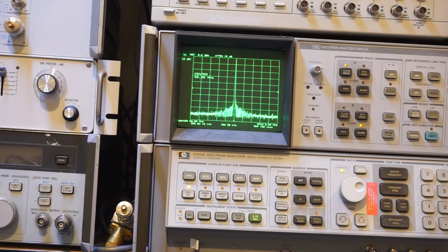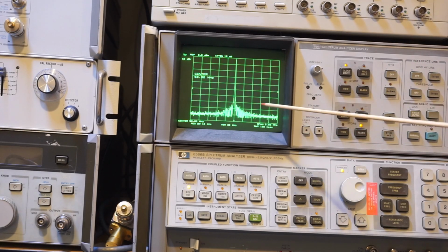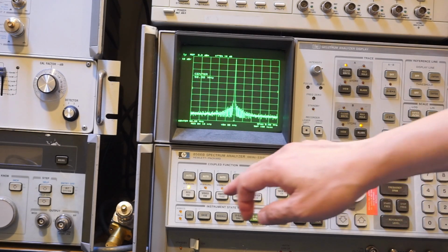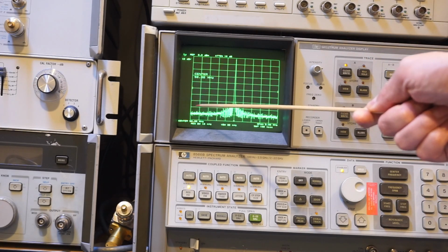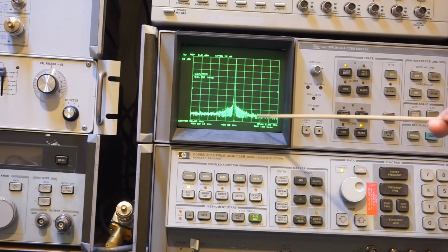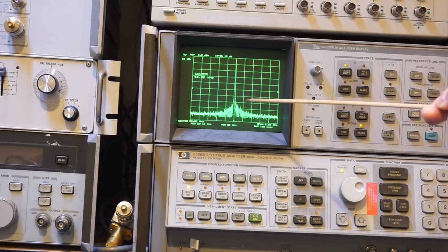And here you are looking at a signal that is centered around 50 megahertz. You can see a frequency span of 5 megahertz, and the resolution bandwidth currently is set at, I think, let's take a look, it is at 10 kilohertz. So that's pretty narrow, and you can see the signal here is essentially very clean. There is some skirt, which is to be expected for any type of DDS signal synthesis, but you can see that the signal is very clean.